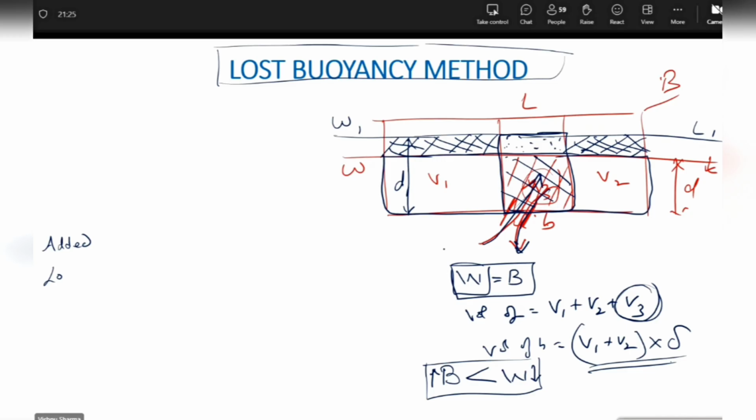But when this compartment in the midship is bilged and seawater is filling into it, then it is not displacing seawater. No, it is allowing the seawater to fill in. Correct? Yes or no? Yes, sir. Now it's in contact with the seawater, and it is filling up with the seawater, so it is not displacing. It will displace seawater only if it was intact.